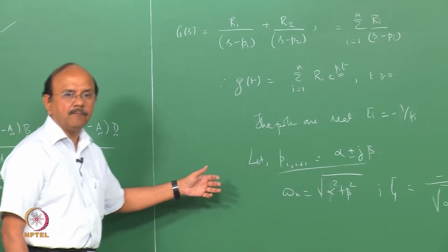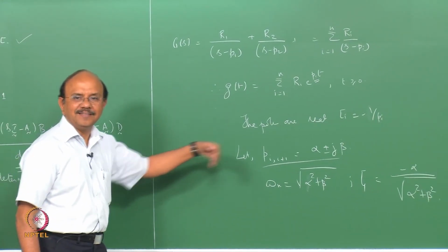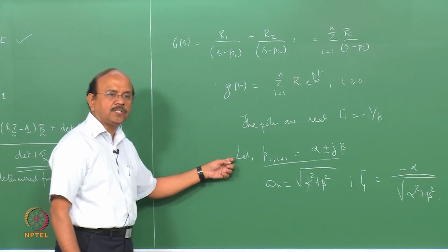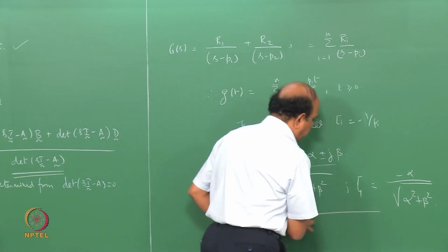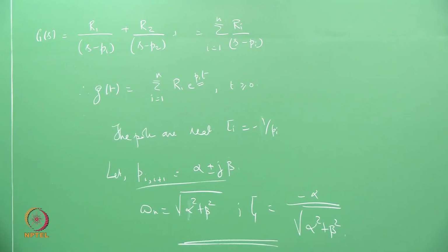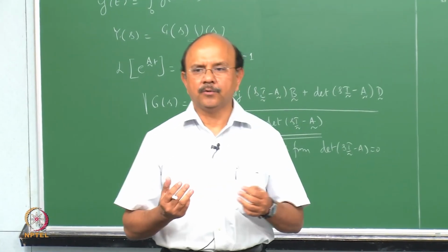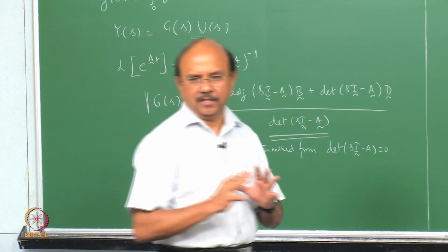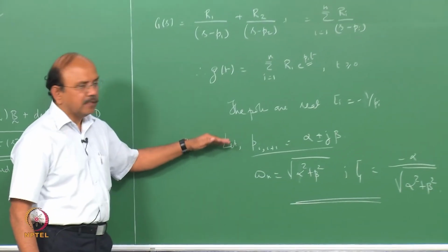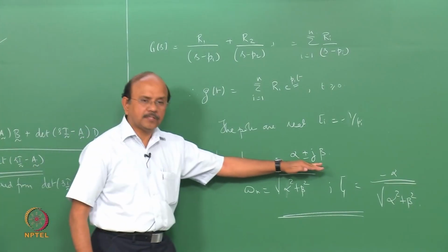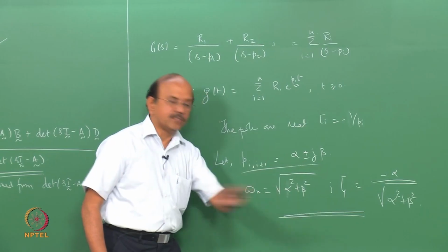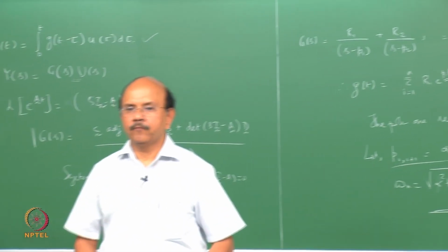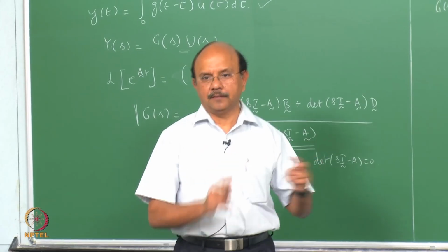And more importantly, if you want to pick the relationship between the poles, the natural frequency and damping, then the relationship is given by this form. Okay. So people usually say that natural frequency is the eigenvalue or poles and so on. They are not strictly correct. Yes, one comes from the other, but please note that if these are the complex conjugate poles, then this is what is the natural frequency. Okay, now you understand the natural frequency and the poles.